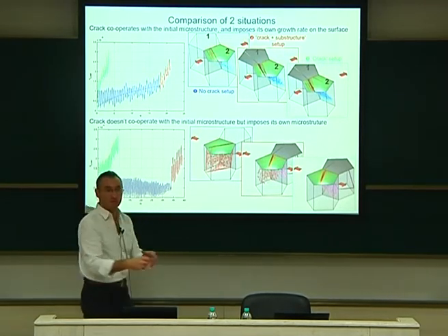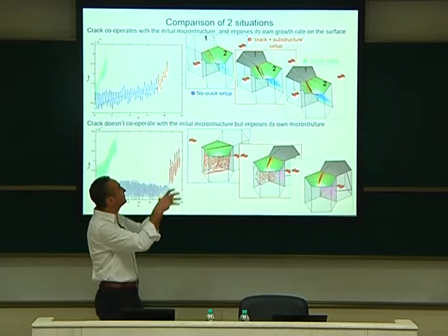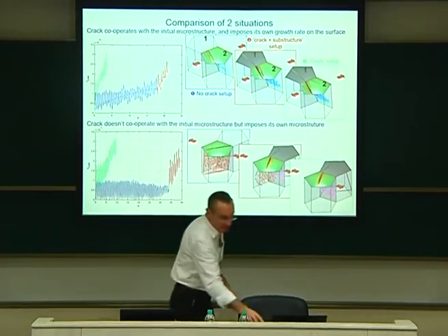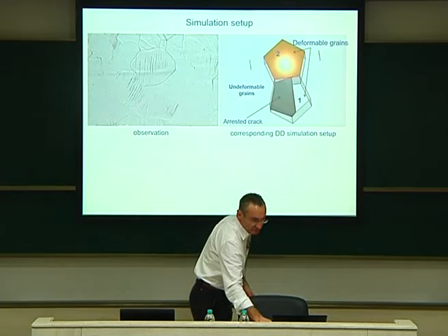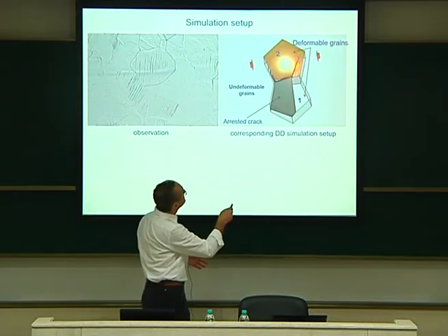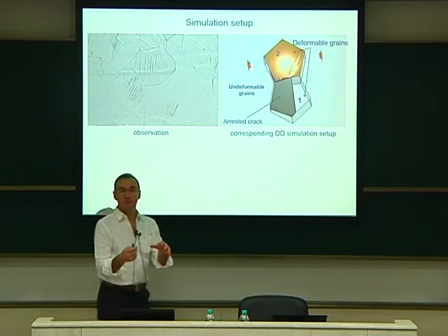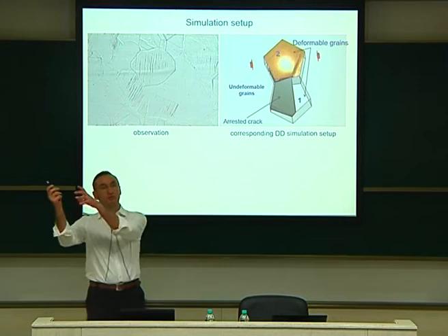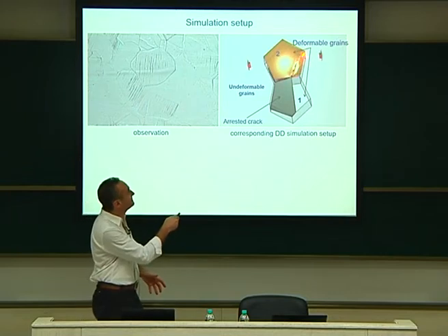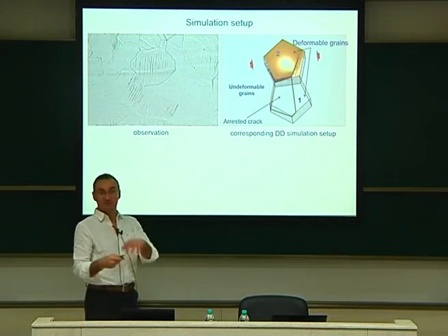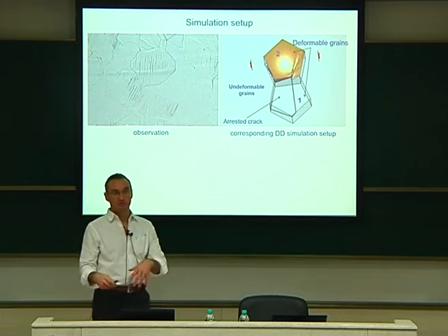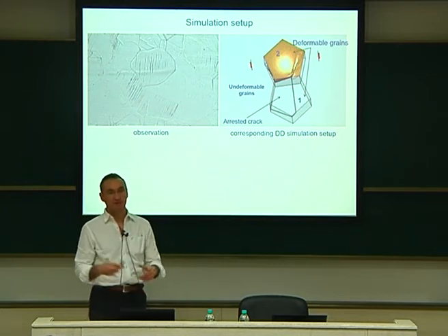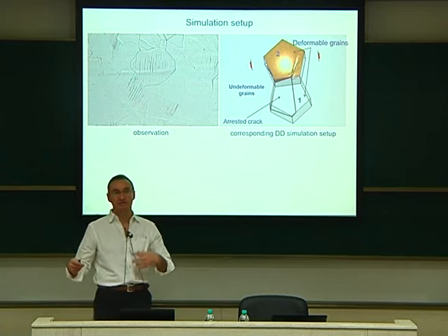In that plane, I'm sure you have some channels leading to extrusion at the surface. We see it clearly maybe in the movie that I showed before. I think there is a movie here. You see the extrusion here. You can see the extrusion is forming, and this is just because of these prismatic loops coming out at the surface, and this creates this extrusion. Okay, we don't put it ab initio. It's also something which is generated by the code itself because of the vein structure and interaction, as I explained yesterday.